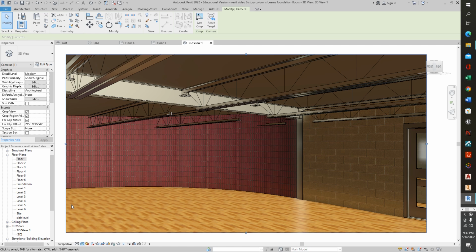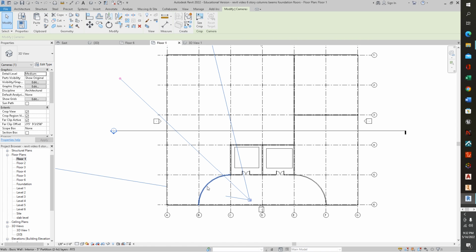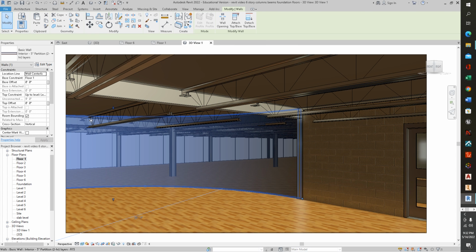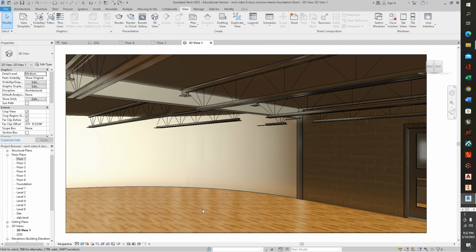And we've put our brick up on the one side. If we'd like to have our tile, as I said before, on the other side, we could actually go into floor 1, click on this, click the direction on there, and that'll put our tile now up in that direction. So one side is going to be brick, one side is going to be tile, no matter where you're putting that wall up.